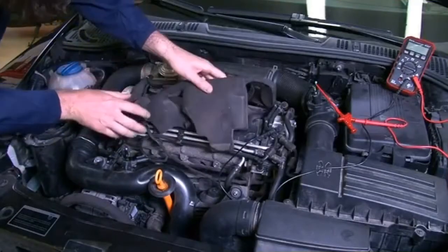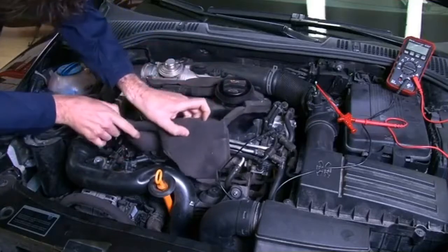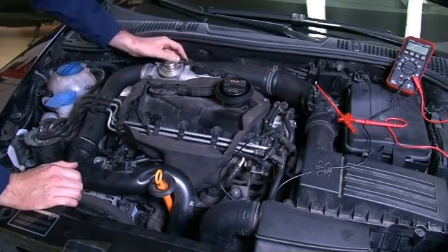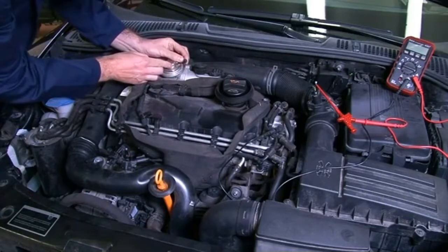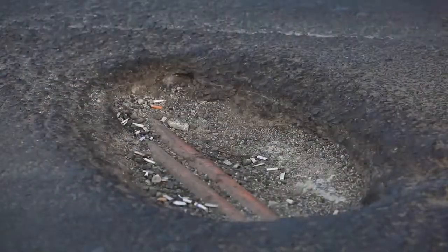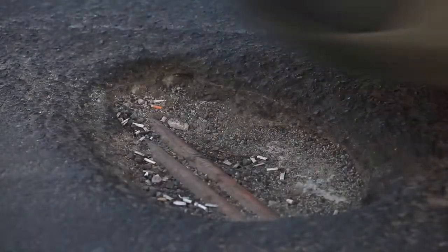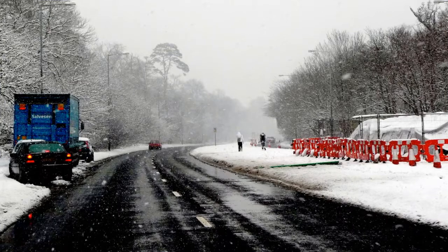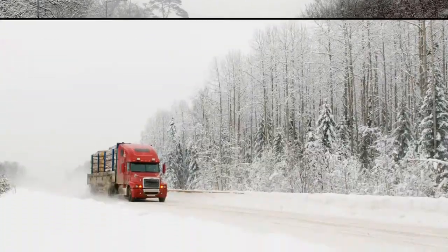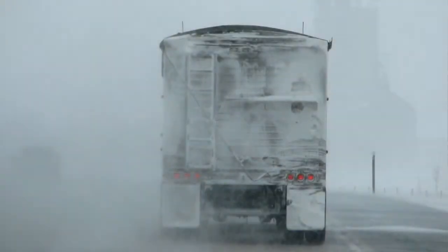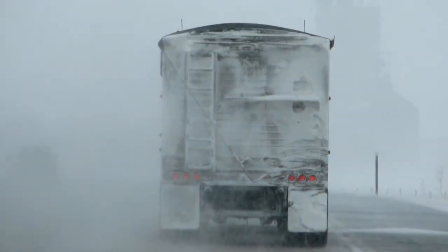Collisions caused by mechanical failure are preventable if the defect was known or should have been known had the driver or technician followed standard vehicle inspection procedures. Throughout the trip, road vibration and the elements may loosen and weaken components. Minor vehicle defects become even more extreme during winter weather conditions. So be sure coolant levels and other mechanical components such as the heater, defroster, and the engine block heater remain functioning throughout the winter by conducting more frequent vehicle inspections.